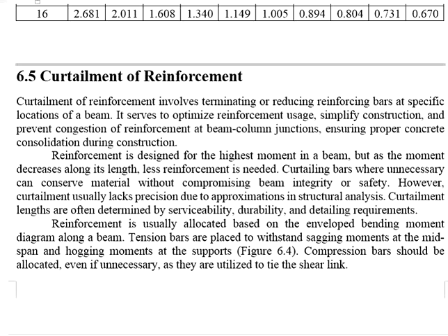It means that when we do this terminating and reduction of the reinforcement bar in the member, the strength and the performance of the member is not affected. We only remove the reinforcement at the regions which is not necessary.